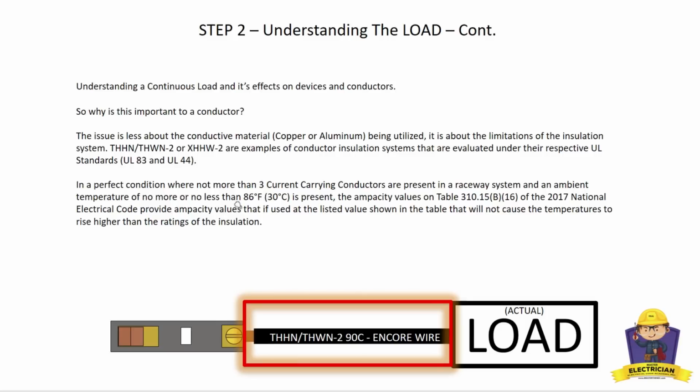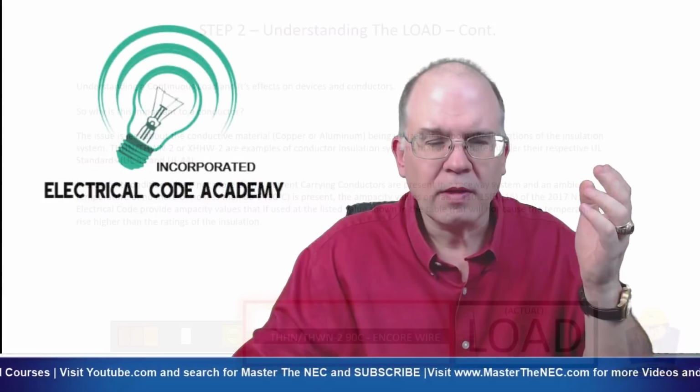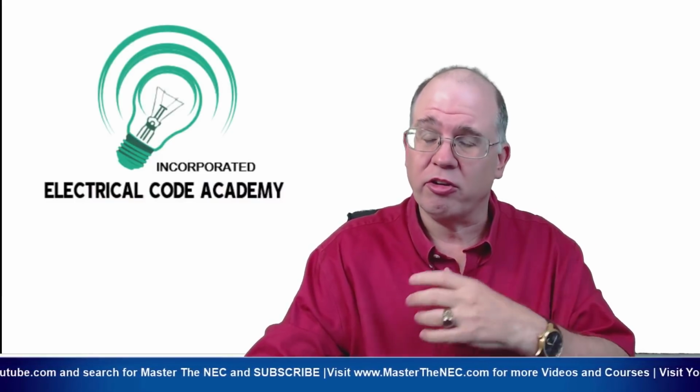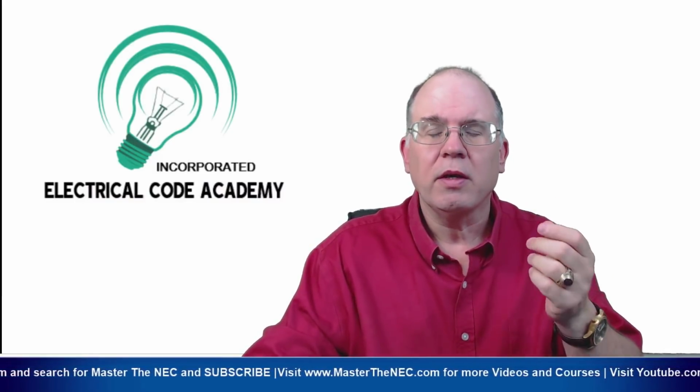Now, in a perfect world where we didn't have more than 3 current carrying conductors in our raceways or cable systems, and the ambient temperature was not more than 86 degrees Fahrenheit or 30 degrees Celsius, then the actual ampacities that are found in 310.15(B)(16) of the NEC would be the actual value that you'd go to. If you do your calculation, you go right there and you pull that value.